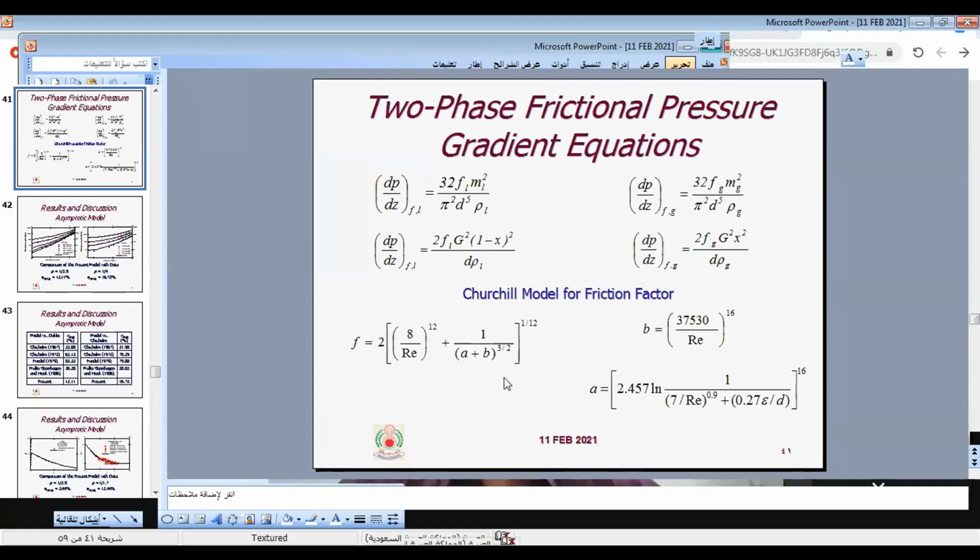for circular pipe. As you know, in fluid mechanics and heat transfer, if we deal with non-circular ducts like rectangular, triangular, square duct, and so on, we use something called the hydraulic diameter, which is calculated as 4 times the cross-sectional area divided by the wetted perimeter. You can see here the constant in this equation. The constant 8 actually represents 16 over 2.